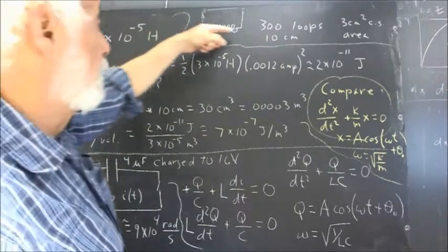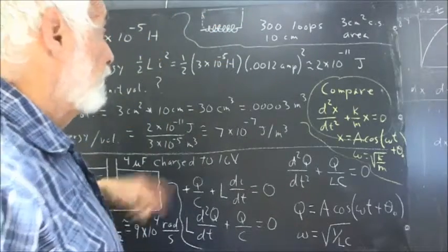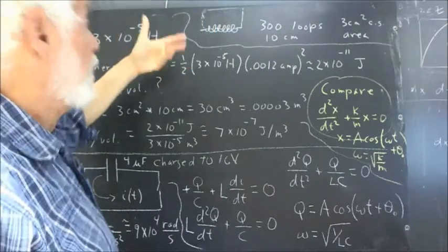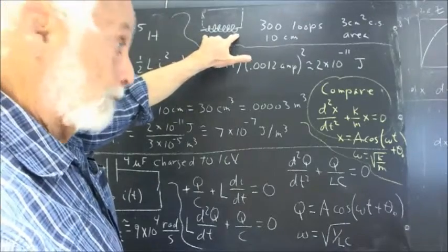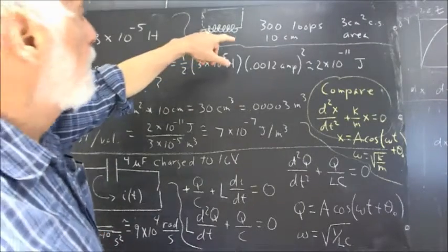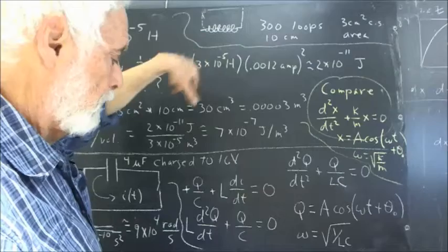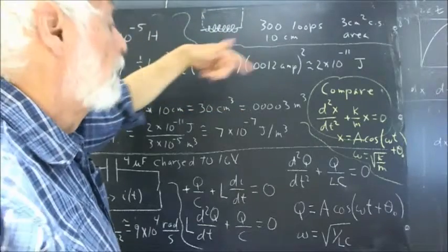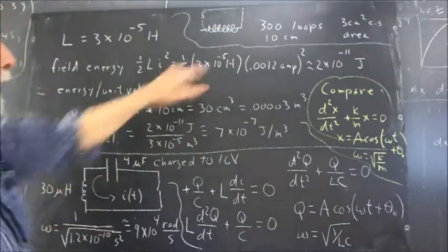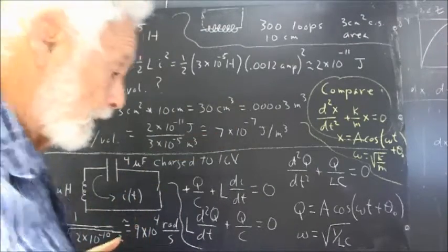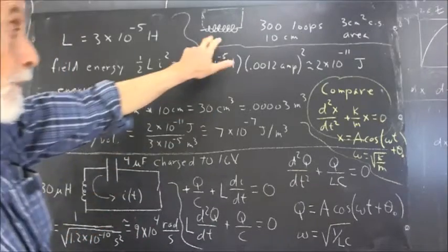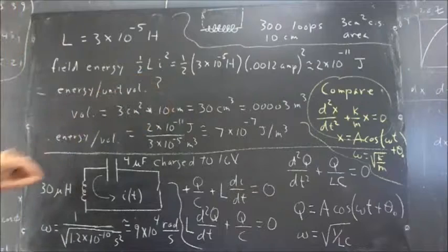The assumption that the magnetic field is uniform within the set of coils isn't particularly accurate, as we said before. If you move away from the central axis, the field varies, and as you get toward the edges, or toward the ends of the loop, the field varies. That could be remedied by putting the inductor in a toroidal configuration, a donut shape. Imagine a donut surrounded by a bunch of wires. Then we wouldn't have the end effects. The entire magnetic field would be contained within, and you see that in your text. The analysis is very similar to the analysis we used here, and it's more valid than this.